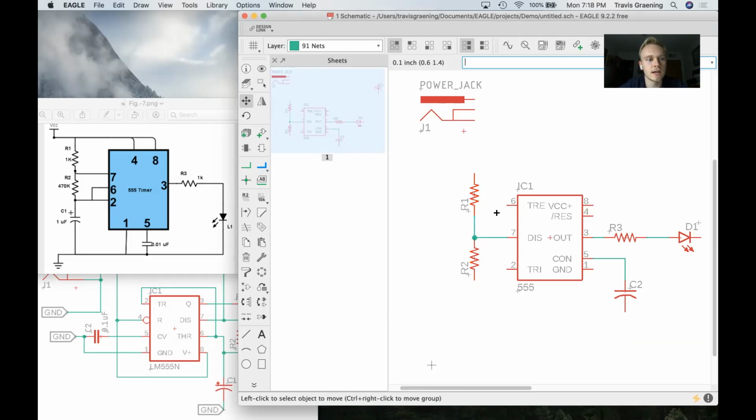And so now we're going to also have a great example of when a connection has not actually been made, because we want to connect pins 6 and 2. So we're just going to draw a cross like this over to number 2. And so even though we're crossing 7, there is actually no connection there because a green dot has not popped up. All right, and we also have to connect pin 2 right here to the side of resistor 2, like this.